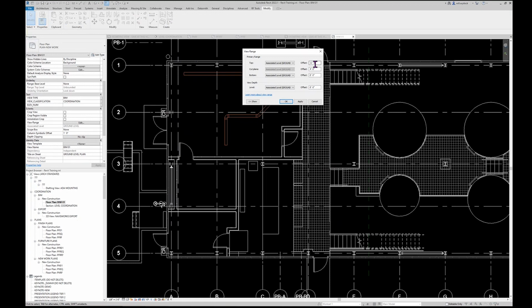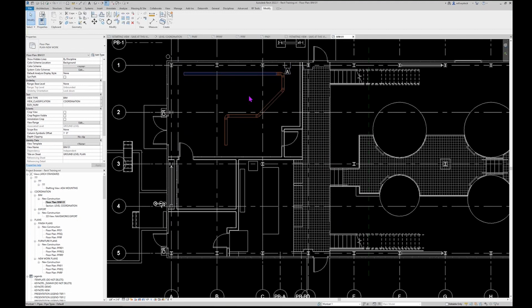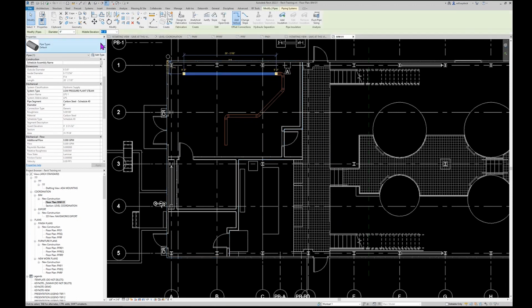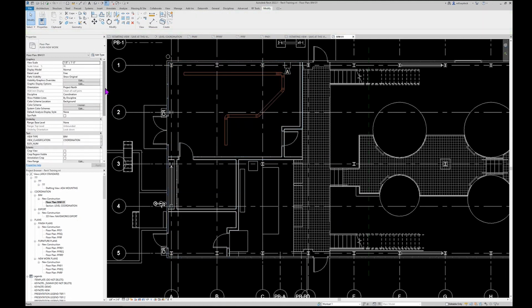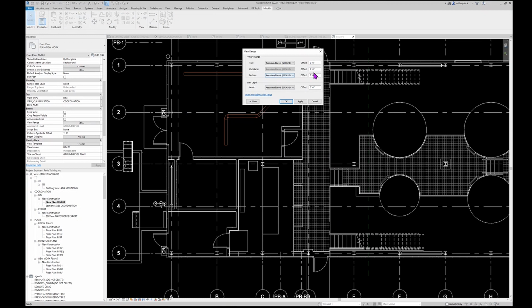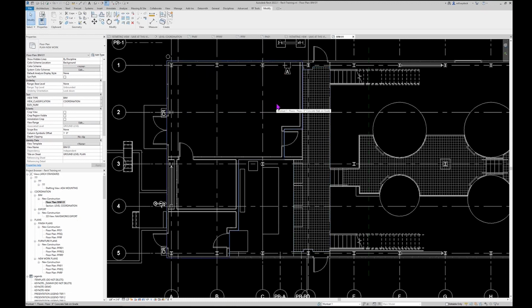11 is great for the engineering side, but on the architecture side, 11 is just overkill because it would be seeing more stuff than you'd ever want to see. So you'd probably want to come down here and just change this to, say, a 9 foot. By 9 foot, I'd be able to get all the graphics. No, wait, can't do that. These are actually at 9 foot, so let's say 8'8", or 8 foot. I'd say 8 foot just for my purpose. The piping I had just drawn would not be showing in view, but I'd have everything I need above the cut plane.